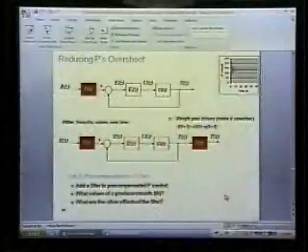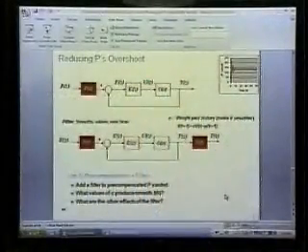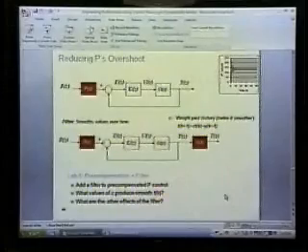Well, it seems like you've changed the measured output, but not changed the system behavior. I've changed the measure. It's definitely a different measured output. It's a smoothed output. So if the system reaches steady state, if it's a stable system, the two systems will have the same steady state value. But their dynamics are different.